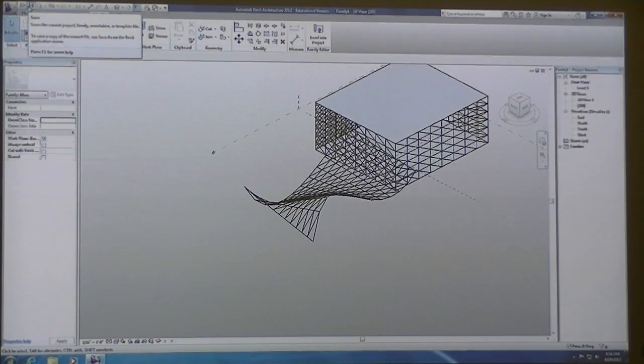What happened is somehow you've applied or loaded this into the same family. Like basically you loaded it into itself. So I'm gonna delete it out of here because it doesn't need to be in this family, and load it in the project. That should fix the problem.